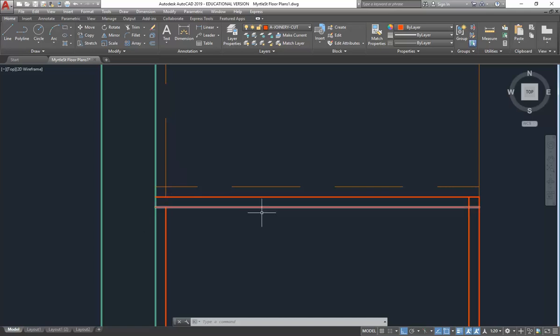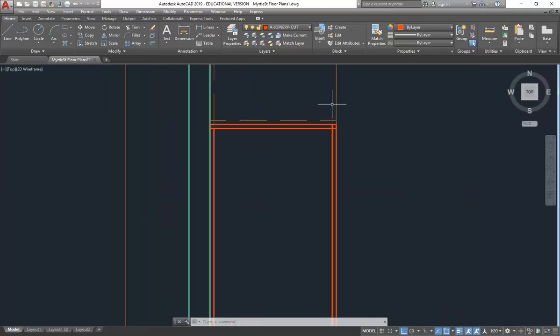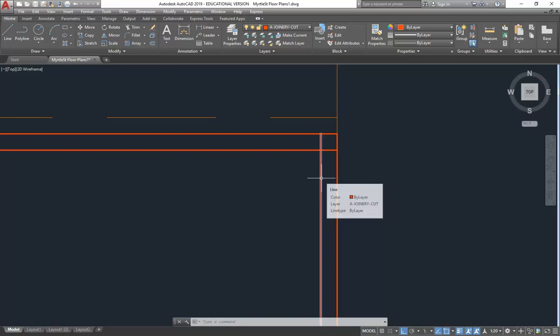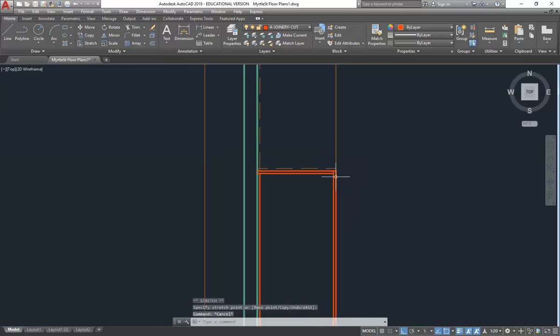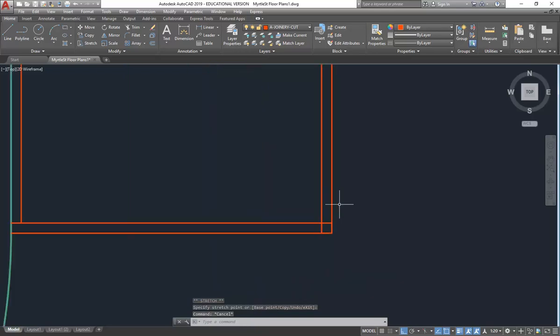And then at the front, you need to know what sort of doors you're using. But generally these days you'll have the doors with the hinges that essentially lift the door out as they open. So that means the doors can be flush with the cabinet, so it'd be like that. And that's a good basic setup for a unit like this that's got exposed sides.